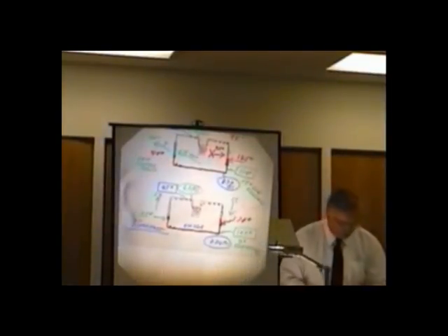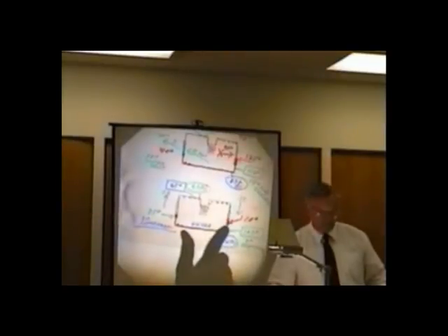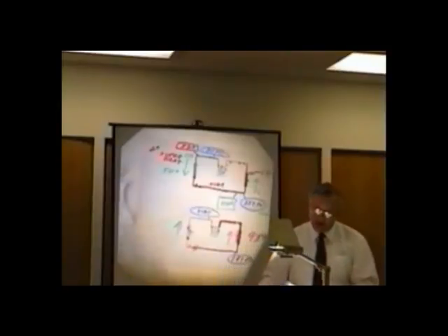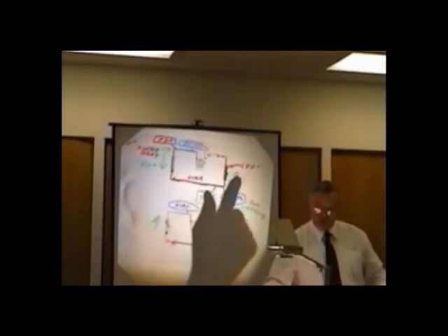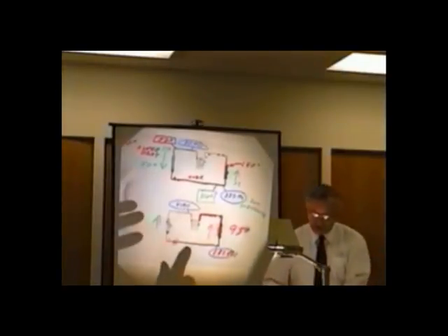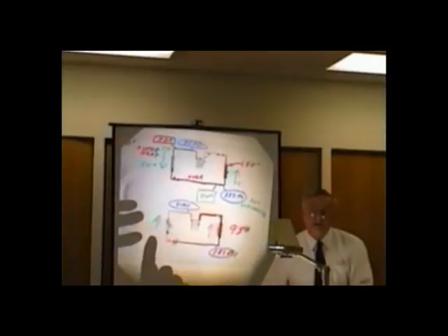Ladies and gentlemen, it's the terminology that throws you. You say up and down and superheat, and it's all confusing. But watch now. Let's go back and review. Undercharge: subcooling is down, superheat is up. On an overcharge, subcooling is up, superheat is down. On a restriction, subcooling is up and superheat is up.